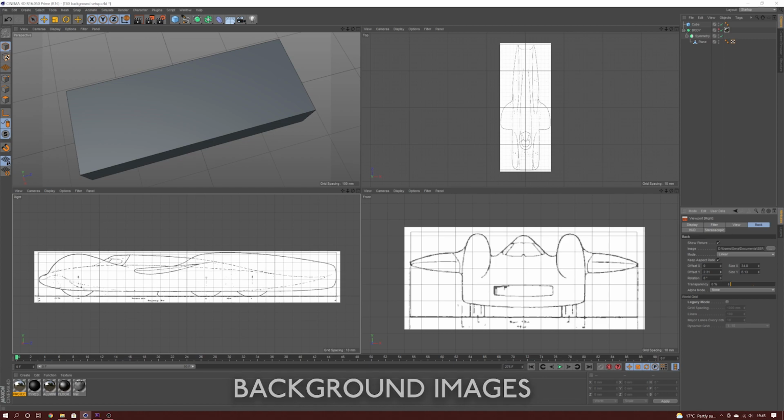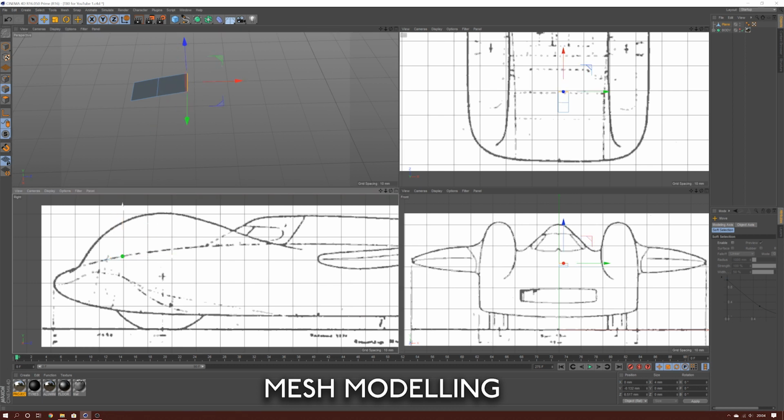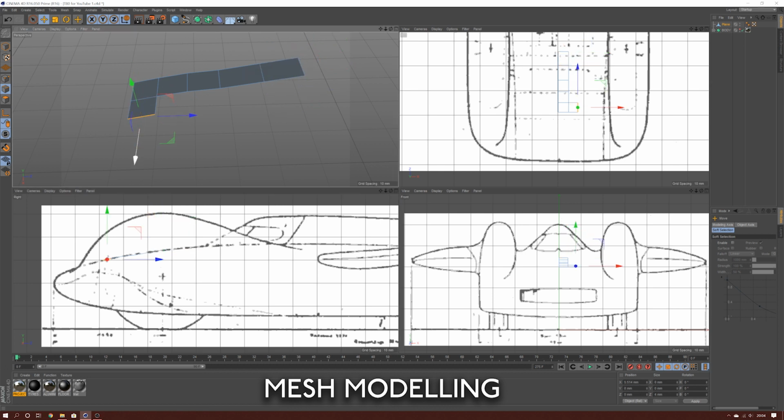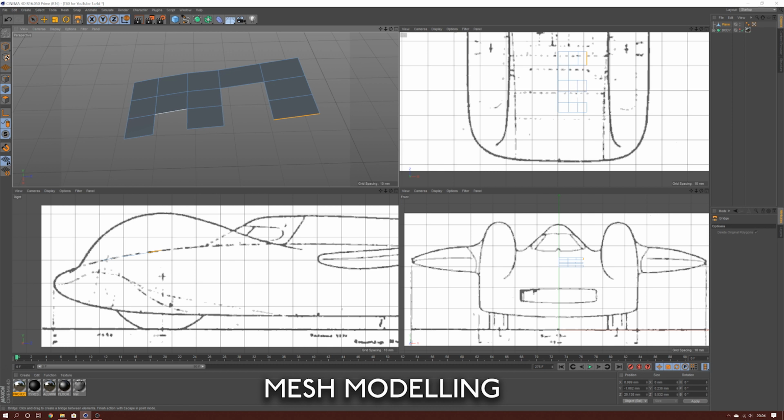Now we can start making the car body. This is the most common technique to model an organic mechanical form and is available in most software. We start with a plane, just a small, flat square. Aligning one side of this plane with the centre line, we begin extruding it in stages to trace the profile of the car. As we go, we can adjust edges and points to try and recreate the gentle curves of the T80. We don't have to use the small squares all the time, but it can make it a lot easier to deal with the more extreme curves as the process goes on.